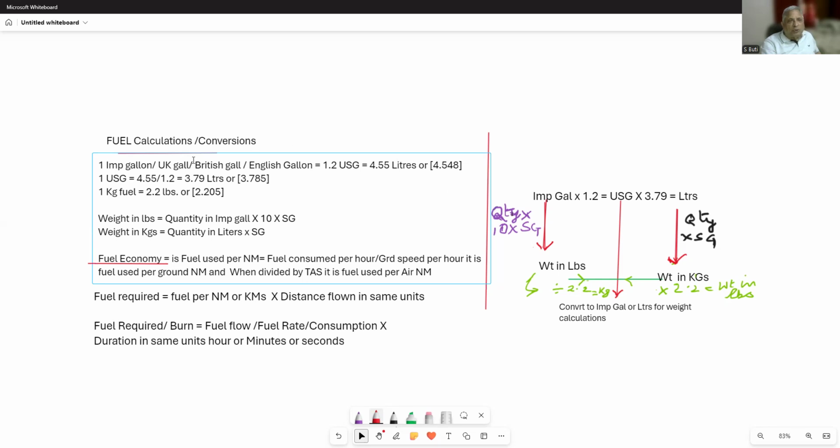So it's a pilot's responsibility to check the fuel before departure or takeoff. And while you are giving instructions of how much fuel you require, give it in the proper units being used by that country or that person who has come to fill up your aeroplane. He may not be as educated as you are, and you need 5,000 gallons or US gallons, and he fills up only 5,000 liters, then you'll run short.